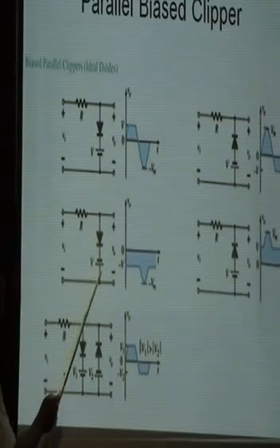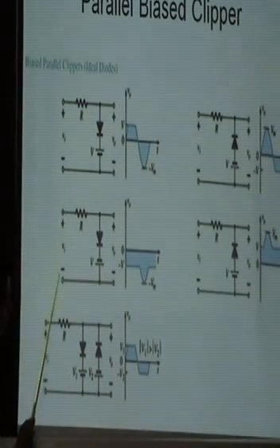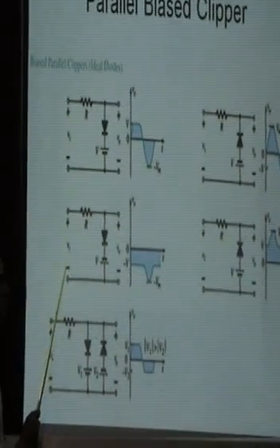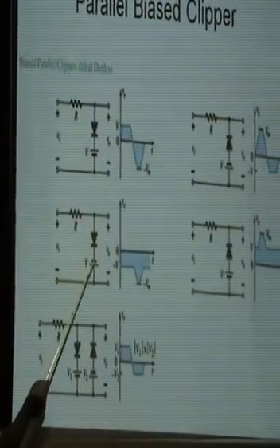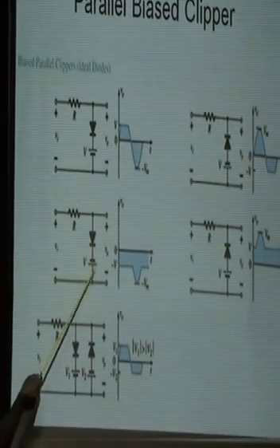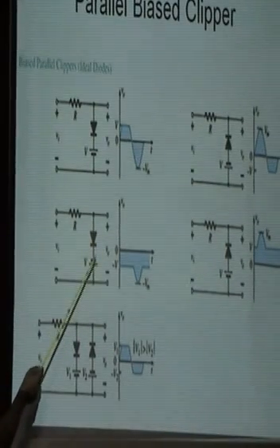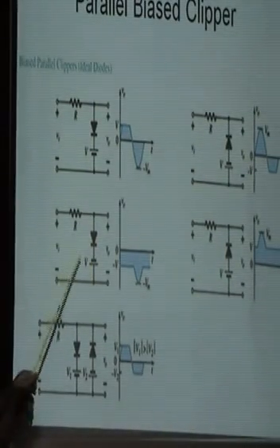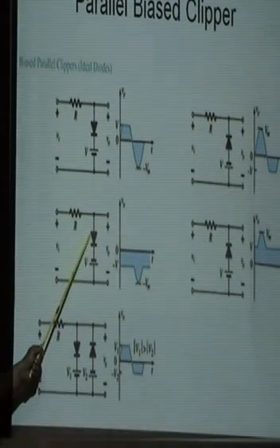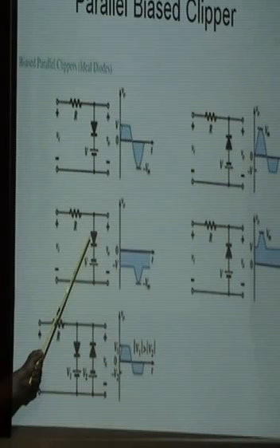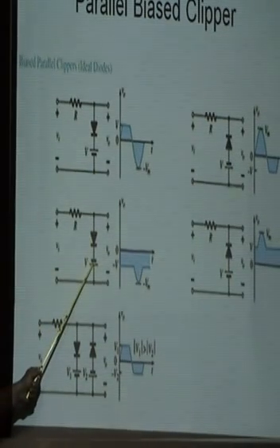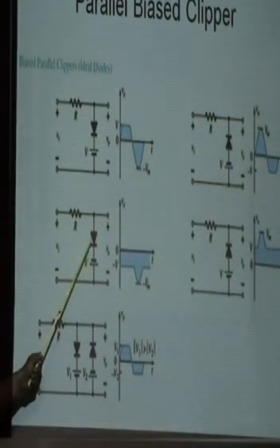So here the battery is supporting in nature, so for the negative half cycle the polarity is changed, and the diode acts as an open switch. So is there any addition of voltage? The battery can add the voltage. Here the concept is quite different from the series clipper. The amplitudes of the diode as well as the battery are added.